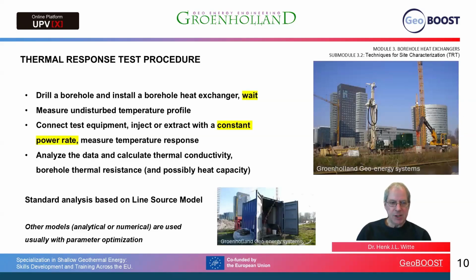The basis of the thermal test procedure is to drill a borehole and install a borehole heat exchanger. Then obviously you need to wait because you've disturbed the underground temperature, you've maybe grouted the borehole and the grout needs to cure. That will take some time, anywhere between 1 week and a couple of weeks.